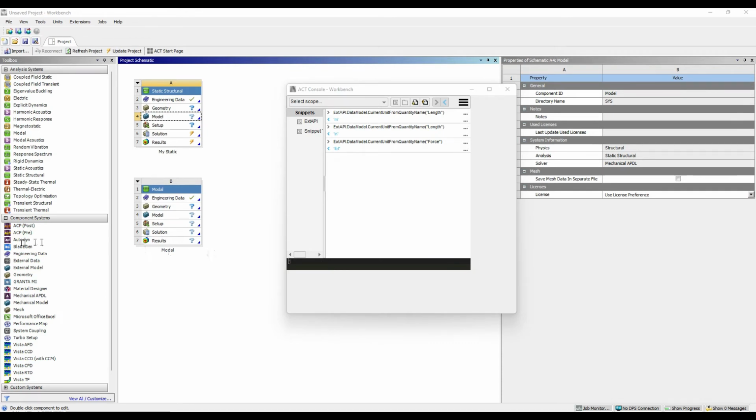So what I will do is I will write this command. It's a 2-line command. So I am using triple quotes to write 2 lines. So here static temp, which is the static template, is this, and to create an analysis system. So I am storing this entire code snippet inside a variable whose name is command. So once I do that, it is stored in command.